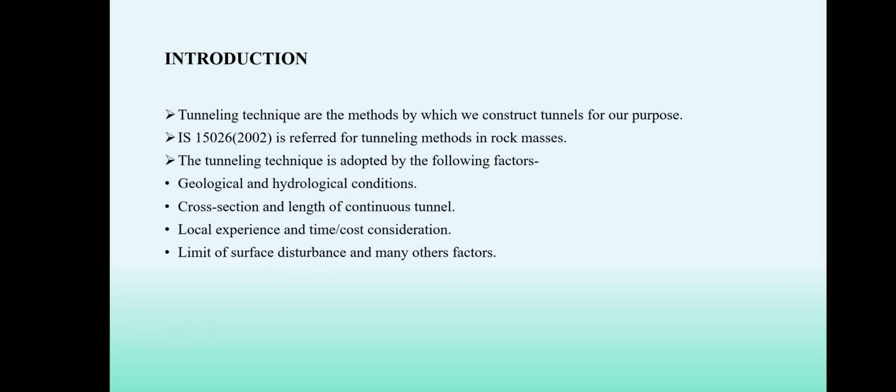Tunneling techniques are the methods by which we construct a tunnel for a purpose. IS 15026:2002 is referred for tunneling methods in rock masses. The tunneling technique is adopted based on the following factors: geological and hydrological condition, cross-section and length of the tunnel, local experience and time cost consideration, limit of surface disturbance, and many other factors.